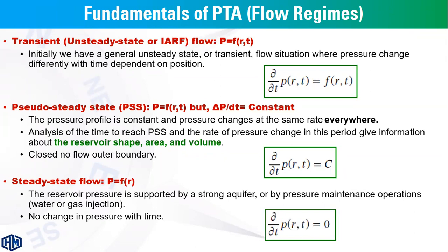In this case, ∂P/∂t, as you can see, is zero, which means we have no change of pressure with time, which means we have very strong pressure support from an aquifer or very effective pressure maintenance operations like water or gas injection.